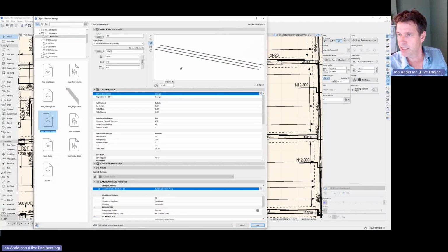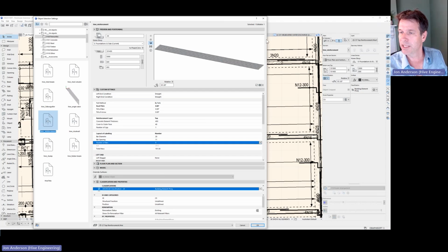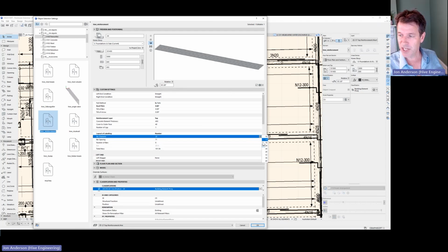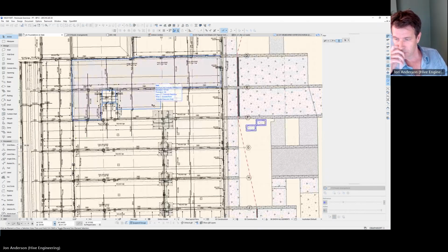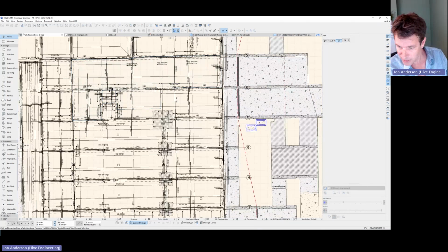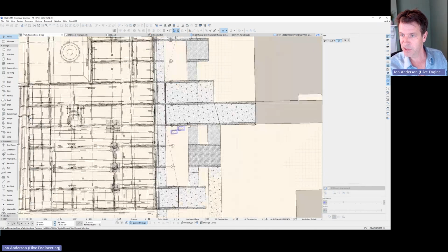Yes, so I can get a group of elements and then change the number of bars in that group, and it'll update in 3D and 2D at the same time. And you can see I'm getting the quantities of the mass of reinforcement at the same time. So I can use the scheduler to get all of that information out for the whole project and work out what the reinforcing quantities are, which is pretty powerful, really. So I think that's a fairly good demonstration of that.